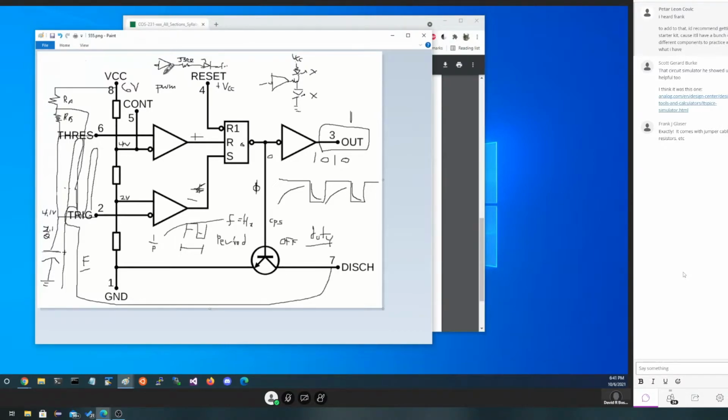But once we get it high enough that we don't see the off times and we make it smooth, PWM basically gives you a full-on LED, and we can control the brightness by varying only the duty cycle. We won't really vary the frequency, we'll vary the duty cycle of the device, like a 555 timer that's producing the pulse wave. So that's one of the uses of a 555 timer. Anybody have any questions about that comment?